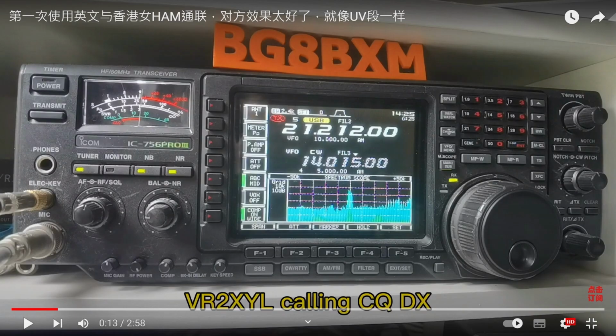And they are not using CW. Okay, USB. So USB is not the USB drive, but it refers to upper sideband. So when we use AM for transmitting a signal, you're actually using both sides of a band. To save some bandwidth, we sometimes just use a single sideband, SSB.